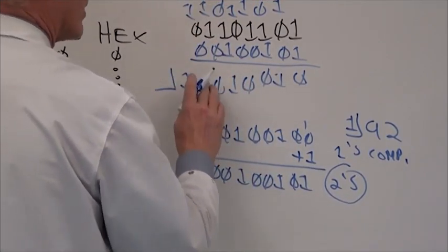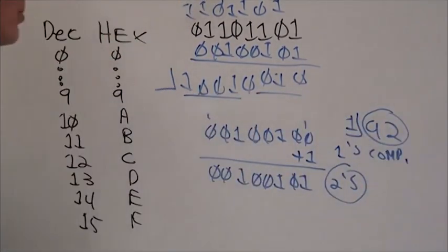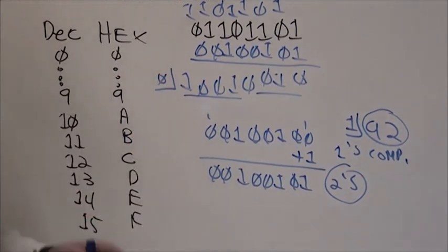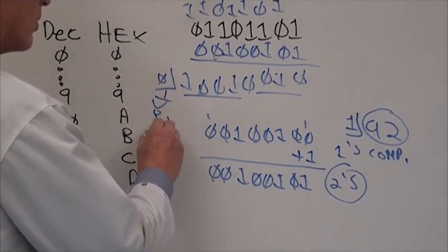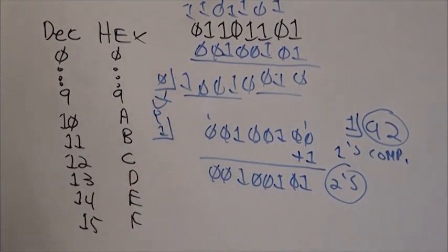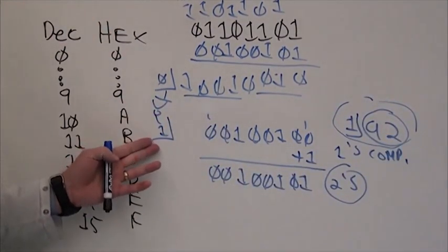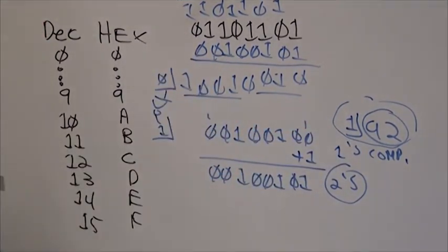And notice our carry here is not right. So we've got 9, 2, just as we had before. But what the digital circuitry is smart to say is, even though we have a 0 carry, it's smart enough to realize that you were doing a subtraction, not an addition. So what it's going to do is run this through an inverter and actually give you a 1. So the intuitive result we came up with, which is 92 with a carry, is exactly what the digital circuitry will come up with, but I think you'll find that this way of doing it in hex is a lot quicker to get your binary subtraction.